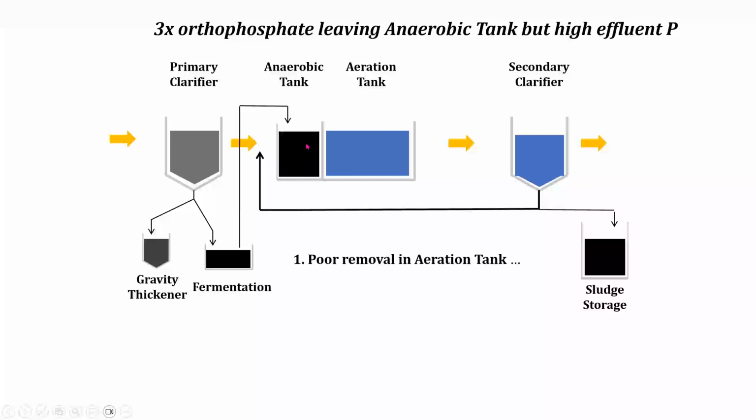More like there's a couple problems that I want to focus on. Is it the aeration tank? Well, if it's the aeration tank, if ammonia is being removed, right? The final effluent is low in ammonia. That makes me think it may not be the aeration tank.